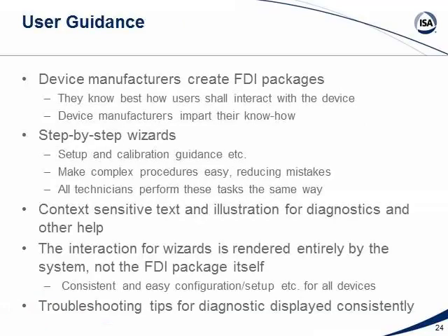Some of the key features that we've built into the FDI is this wizard concept. You've probably seen this when you've installed some applications on your PC, and it pops up a button that says do this, next, and so on. So we take that concept and apply it to device integration. Within the FDI package, in the guts, there are these things called methods. The methods are little procedures that run for typical tasks, like set up and calibrate, to set up the device or do certain complex procedures. It helps guide, in this case, perhaps the instrument technician through that specific function.